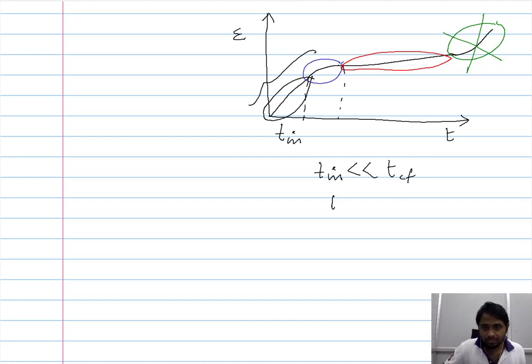The time spent under the transient creep is also not as much as the time spent by the material under the steady state condition. So even though the time spent under the instantaneous creep is much lower than that of the transient creep, when compared to the time spent in the steady state condition, both do not play a significant role. Therefore, the material in its application, particularly high temperature application, spends most of its time in steady state condition. So if we are able to prolong the time spent by the material in the steady state condition, we can ultimately increase the life of the material at high temperature.